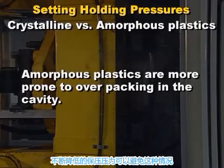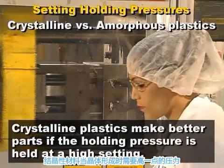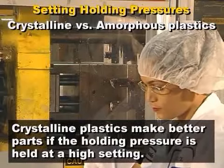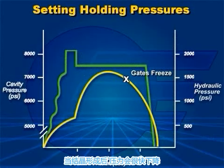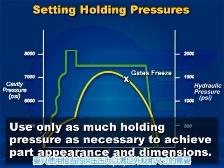A decaying holding pressure profile can be used to avoid this. Crystalline plastics often make better parts if the holding pressure is held high while the crystalline structure is formed. This enhances dimension control and promotes a uniform crystalline structure. After the crystals freeze, the holding pressure can be reduced fairly quickly. The molder should only use as much holding pressure as necessary to achieve the part appearance and dimensions.